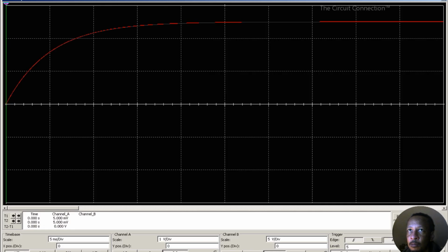So, as we thought, halfway up through this, we said for the charge up, you're going to have both resistors included. So that's your 25 millisecond time constant, your charge up time span, which is your 5 time constants for that particular circuit configuration. And so let's go to 25 milliseconds here.